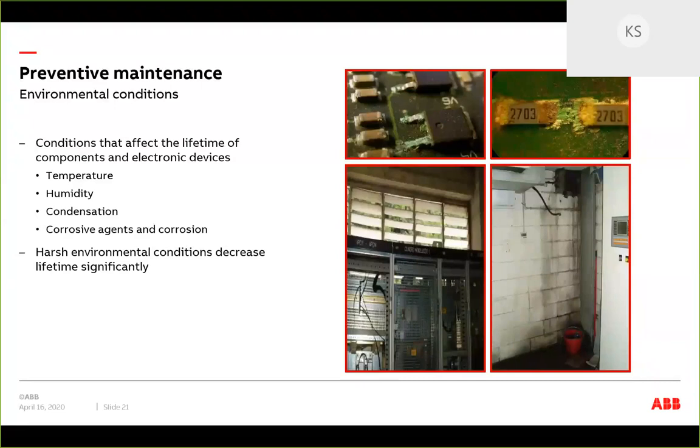One of these customers refined corn, and we had a bunch of centrifuge drives, and every season when harvest would come in, in those plants you get almost like a molasses. Everything gets covered, the cabinets, anywhere you're moving that air, and they were literally taking the boards and putting them in a dishwasher. They didn't put it through the heat cycle, but it washed all that molasses off,